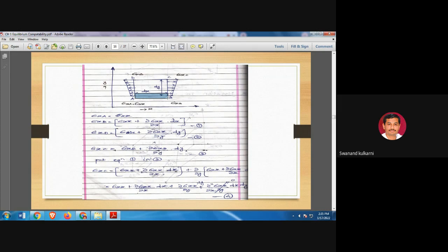That partial differential equation is a differentiation of this sigma x at point A with reference to x at a distance of dx. So that's why the stress present at point B is considered to be sigma xx plus dou sigma xx upon dou x into dx. Are you getting this particular equation number 1?